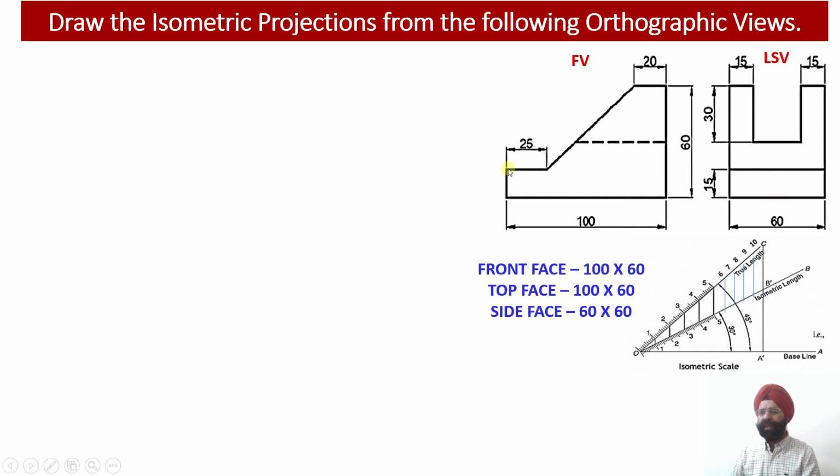Then the second element: you can check that this particular solid is going to have two vertical webs over here. So this is one vertical web and this is another vertical web. Even though from the side view it appears to us as a vertical web, when we look at these two webs in the front view, we find that these are sloping webs.